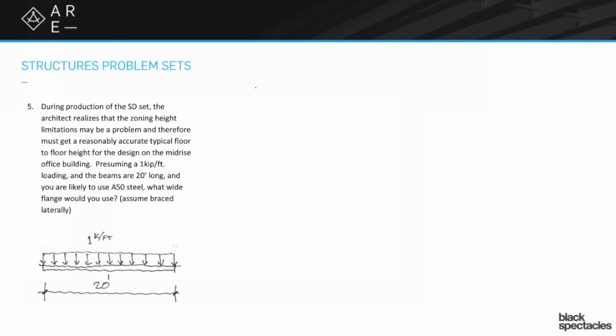So, okay, there's a couple of things. For one, we have to do some quick calculations. We do, yes. And then beyond that, we're going to have to do some other stuff as well. Yes, we are. So let's just dive right on in. So one of the equations that you're going to need to know is moment for a simple span beam with a uniform load, and you've hopefully come across this once in your lifetime, but it's WL²/8 is the moment equation.